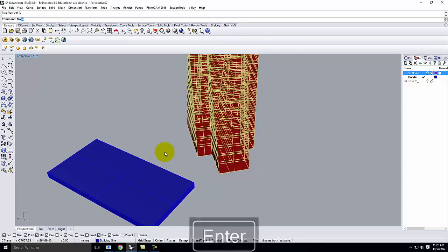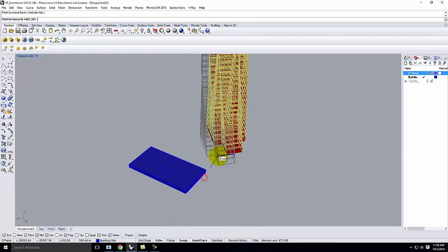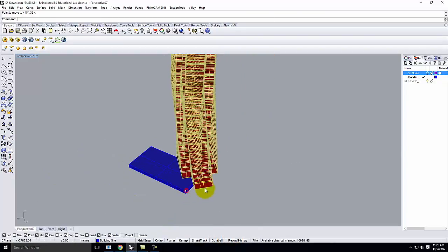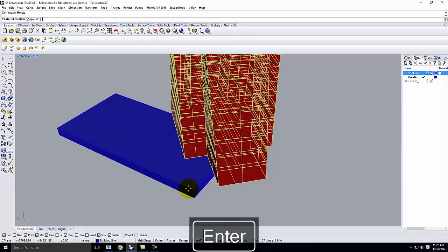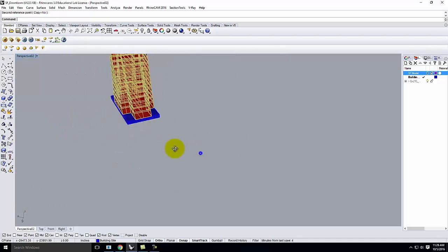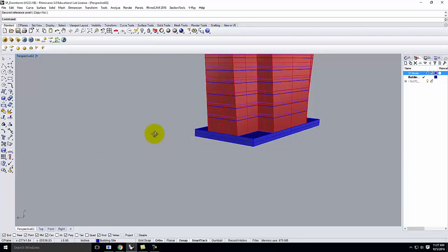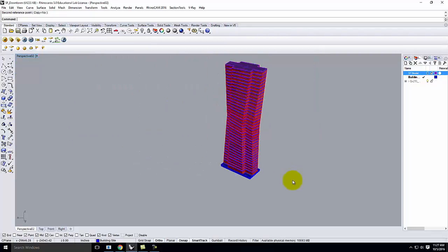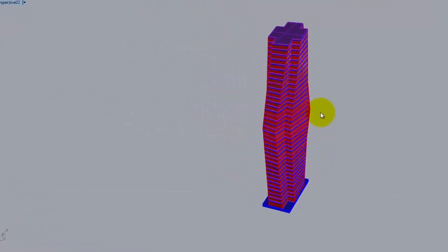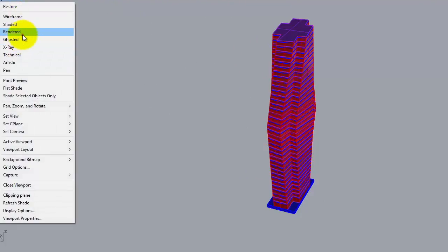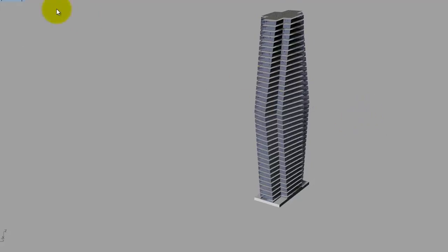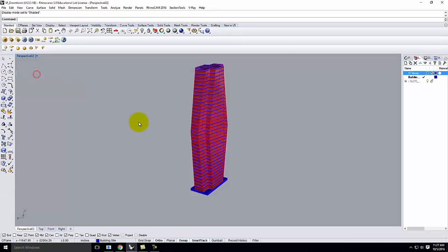And then we'll go ahead and use the move command there and there. And we'll snap to that corner. Then I need to rotate it so that it's in line with my building site. Okay? I gave you a base of 100 by 200 so that it fits nicely. Okay? And we could see the building, and all of that's great. If we switched into rendered mode, right, we'd see all the materials that I had applied to the building, which is what we want. I'm going to switch back into the shaded mode for right now.